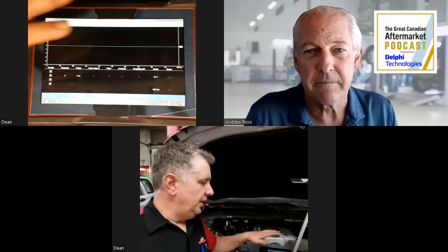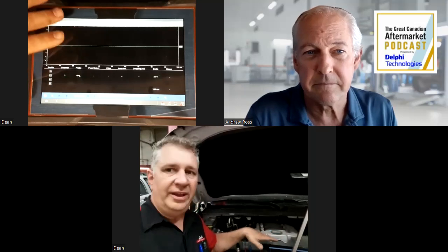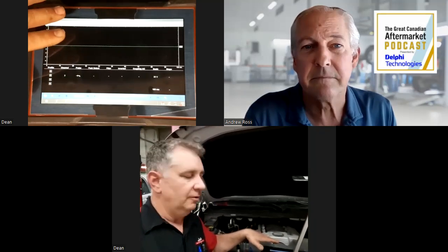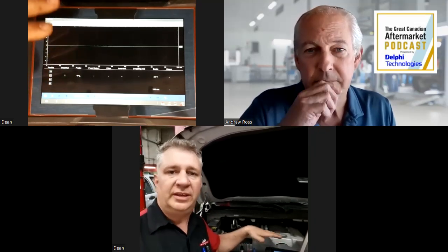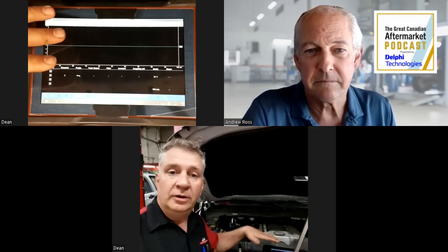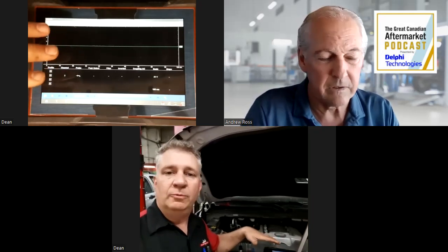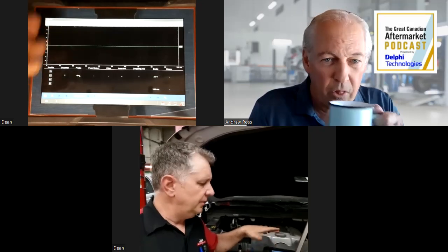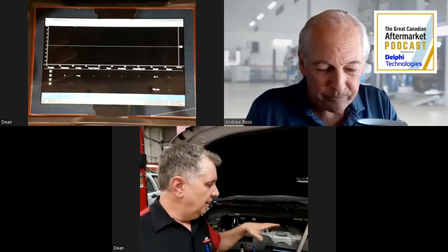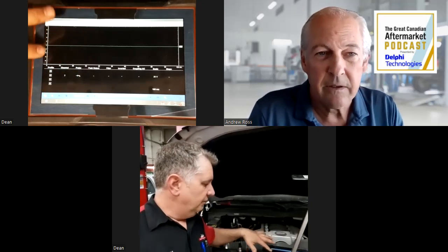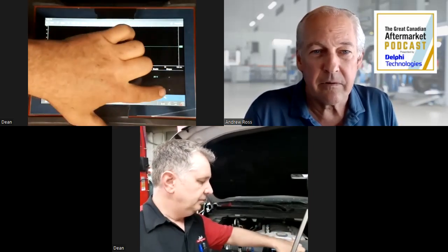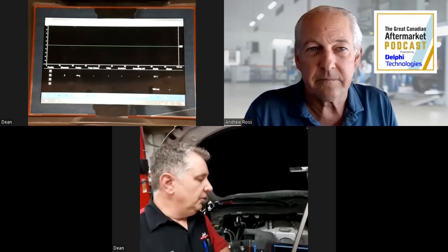Absolutely, Andrew. What we're looking at is just a basic scope at the 20 megahertz bandwidth. That means it's just a basic amount. Pico has the same bandwidth, better sampling rate, but I'm not going to get into that right now. This one shows your voltage over time, your time in seconds down here, and your voltages. So that's what we're looking at.